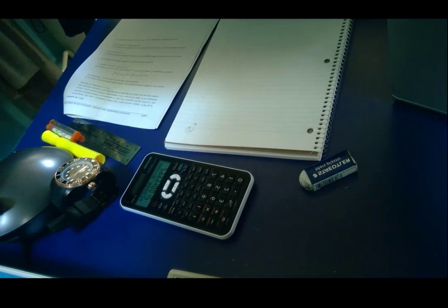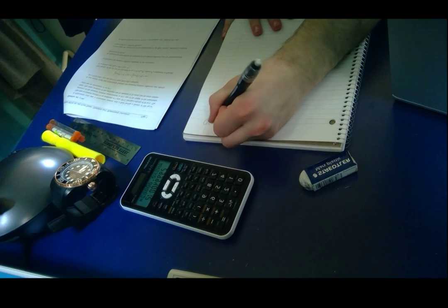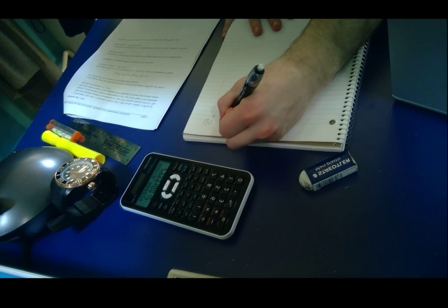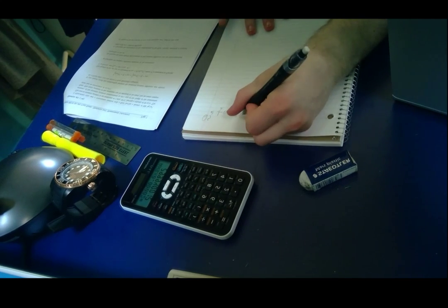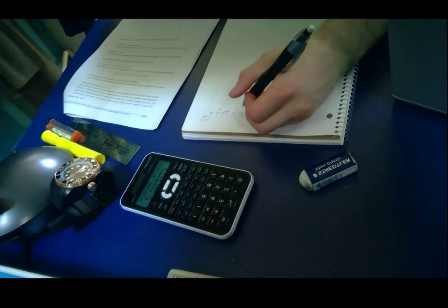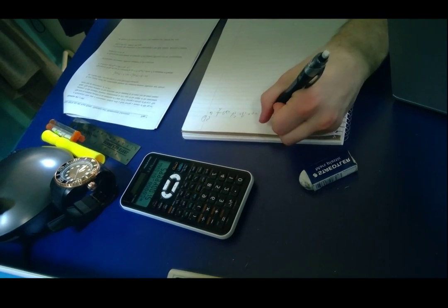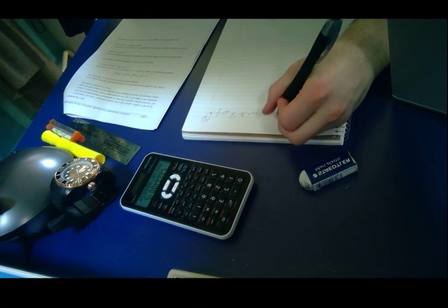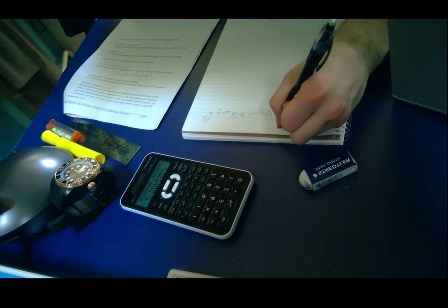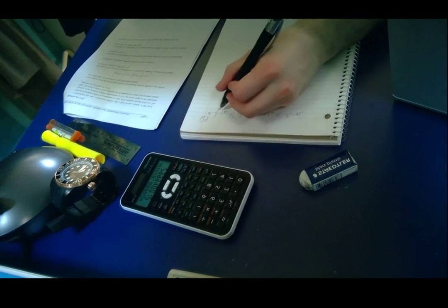Now, A. To first calculate A, we absolutely need to find the equation using Bernoulli's equation. All right? So I will derive it using Bernoulli's equation. Now, there's a couple things we assume here. So this is a pitot-static tube. One of the two velocities is 0. And then we assume that the Z will actually cancel itself because that's the same height. So these cancel, and this one is 0.